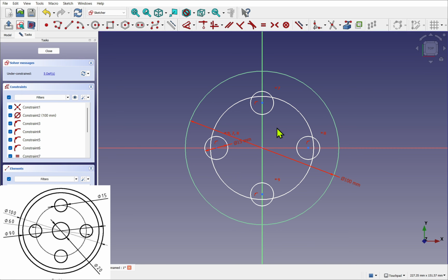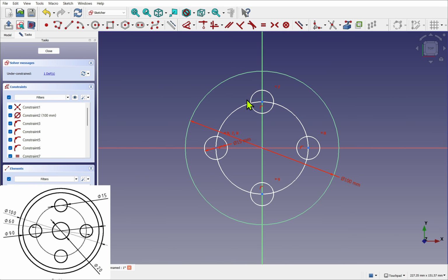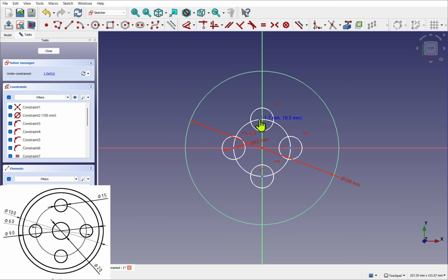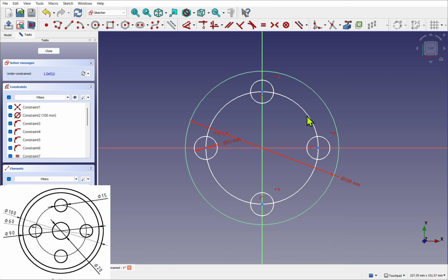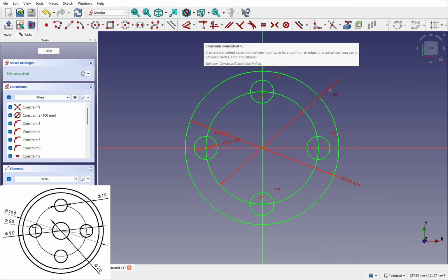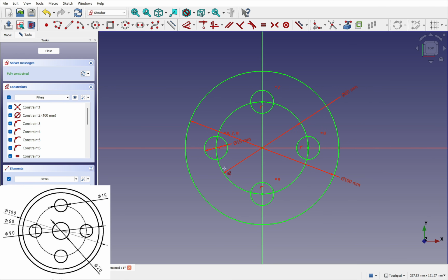Let's right click to cancel. This circle is just going to be scaffolding. So make sure nothing's selected. I'm going to take each of these points of the circle, which are currently point on object constraint to these axes, and then select the circle, and then use a point on object constraint. You can do them one by one if you wanted to. These are now attached both to the axes and the circle. So just by dimensioning this circle here, using the dimension tool, and setting it to 60 millimeters, I've locked down all of these circles in here.